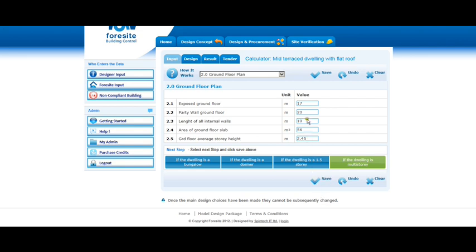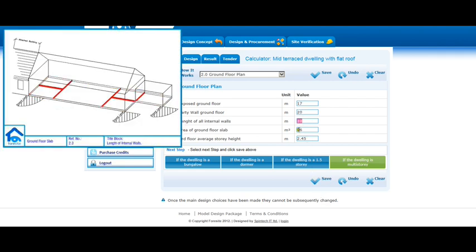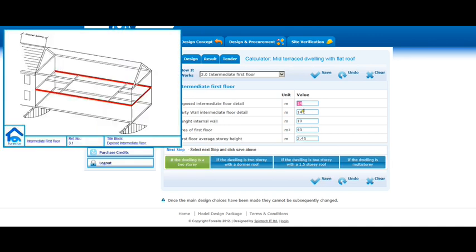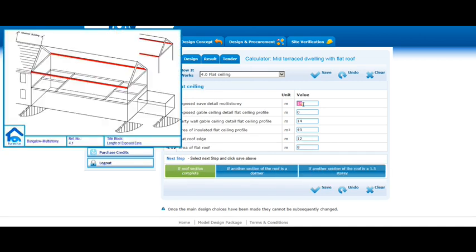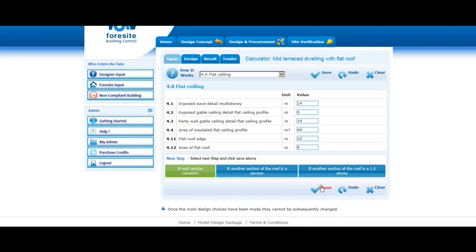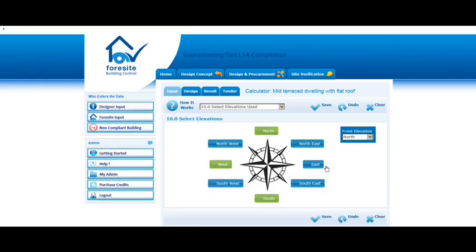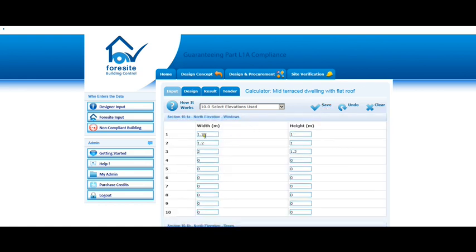As you can see, there are a lot of construction joints with this type of dwelling. The extension means that there are more exposed areas than a normal mid-terrace building. The exposed wall and roof areas and construction details make design compliance difficult to achieve. We have more construction details. This project has 3 exposed elevations and there is a small volume with these dwellings. Compliance is also made difficult by contemporary design, which has a lot of glass, and this can cause overheating.